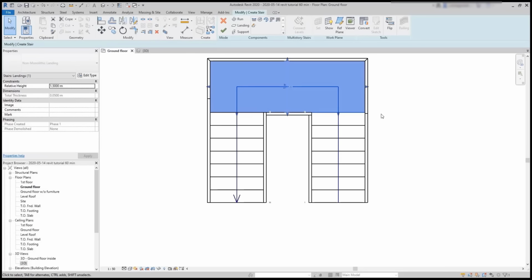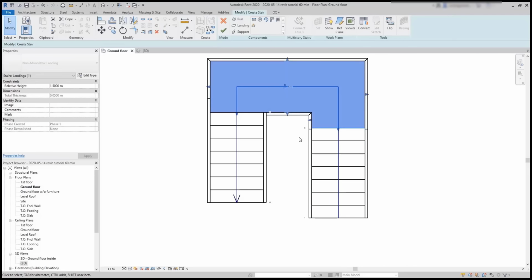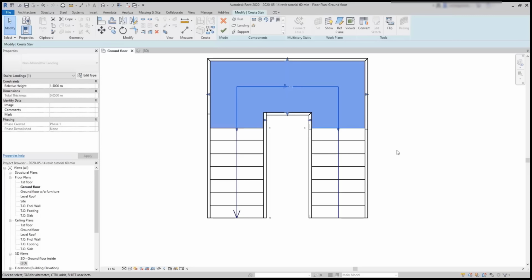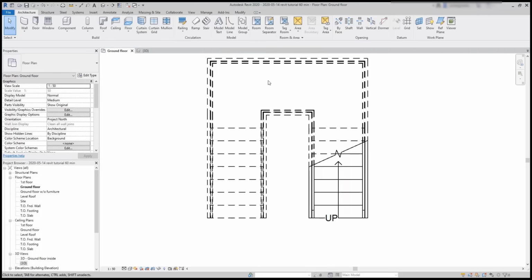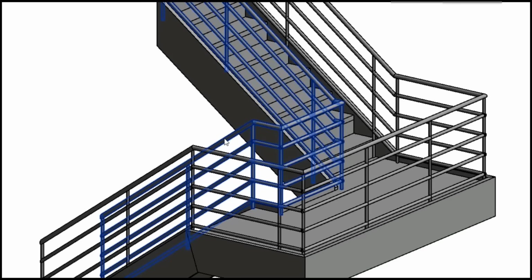and if I click and hold this little arrow, you can see that I am able to extend the landing by dragging down with the mouse, and I can either put the distance that is indicating here or type a specific value. Let's put 0.3, and with that I will have enough room. Then I go to the other side and repeat the process. Click on the tick to confirm the changes and exit the sketch mode. Now I no longer have that issue. And in the 3D view, you can see the railing being continuous and it looks also more beautiful.